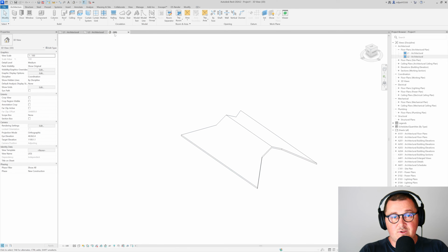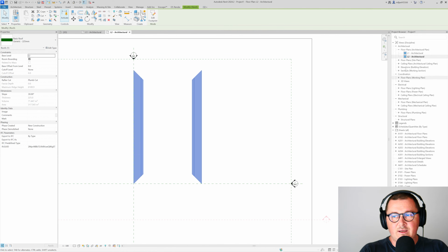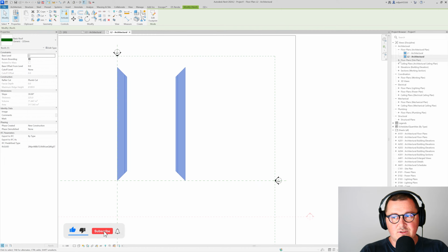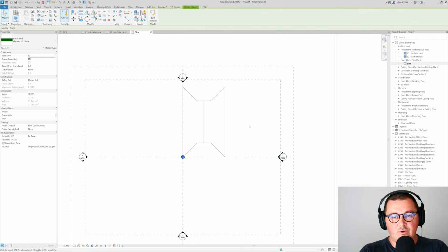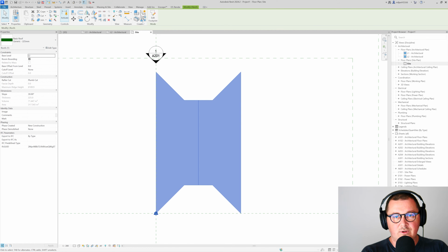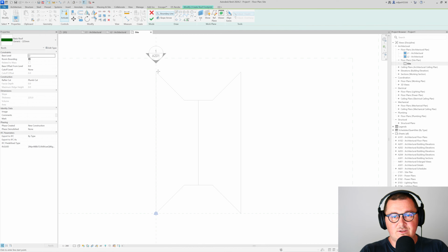one part is done. So what we need to do next is to select our roof. I'm on the second level, so I placed the roof on the second level. That's why we see the cut. So I'm just going to open the side view, so it looks from higher above. And then I will select the roof, go here to create similar. I would like to place it again on the second level, and let's just draw the shape.